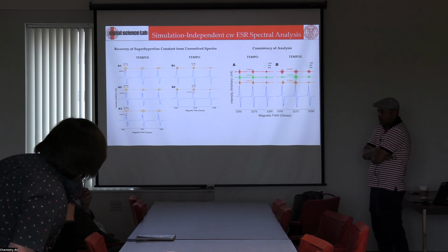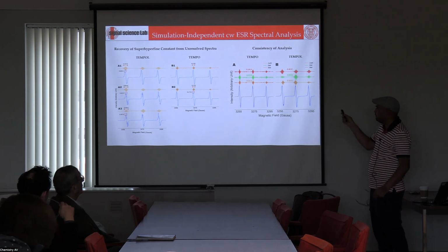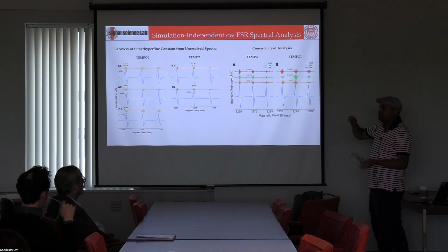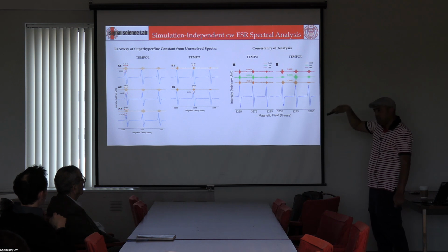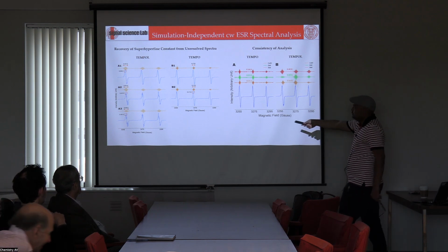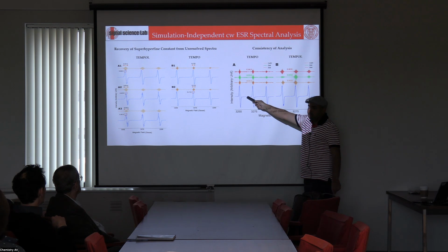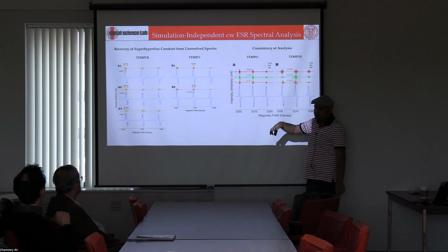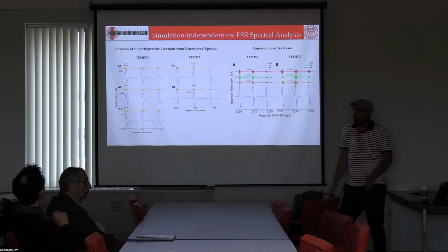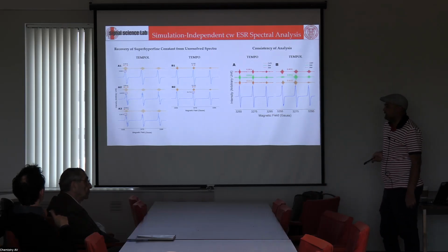When you do a low pass filter and high pass filter, these are special cases of wavelets. In wavelets, we are not doing just frequency, we are adding a time component to it, so it gives you a much more generalized answer. In this case, it looks low pass, but there are some high frequency components to it. If you simply do a low pass filter, it will actually broaden it out. So it's much more generalized in that aspect.